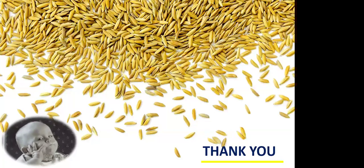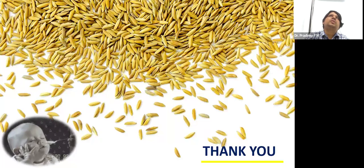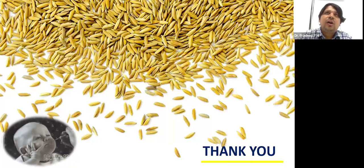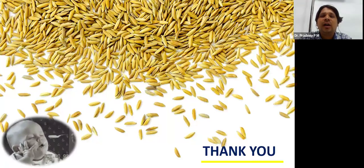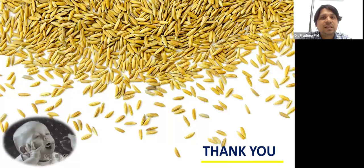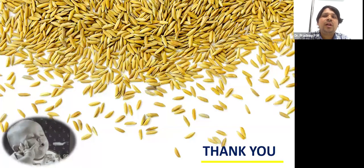And what are the common methods used for drying paddy? Yes, so there are two to three ways. One is the conventional method or the rural method where they go for drying in the sun. So we call it as sun drying. So that is usually a no-no because there may be chances of development of cracks by the harsh radiations by the sun or the heat. So other way is the controlled or in-house drying.